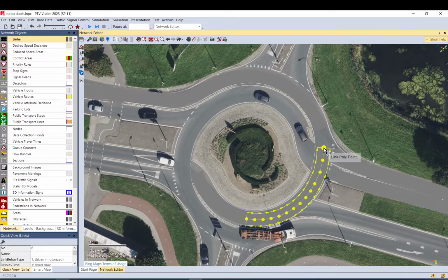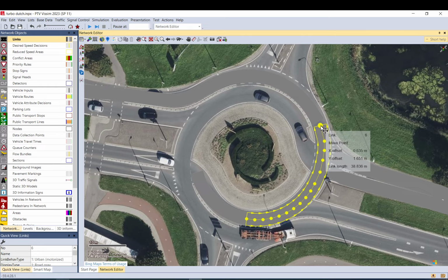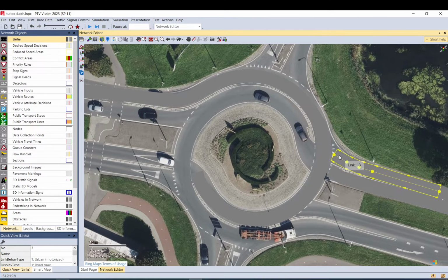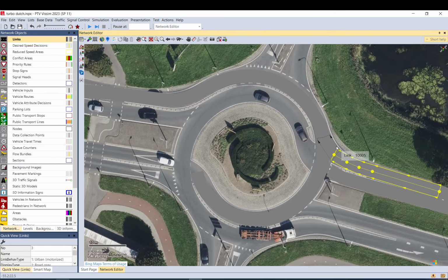The way I would prefer it is if you don't have two connectors overlapping. When you have a link instead of a connector, that will work better if you use conflict areas for Vissim to understand what is what. So if it is a connector, it knows that that is the minor. So it is a bit helpful. But we will use priorities probably. But I might split the video then into two to build that up after doing the connectors now and the network.